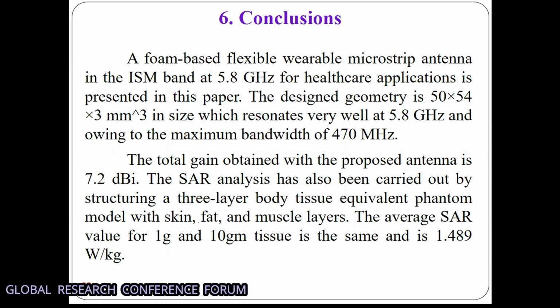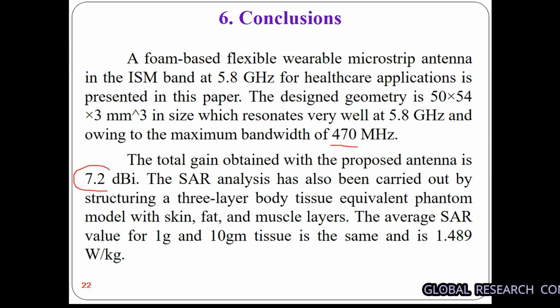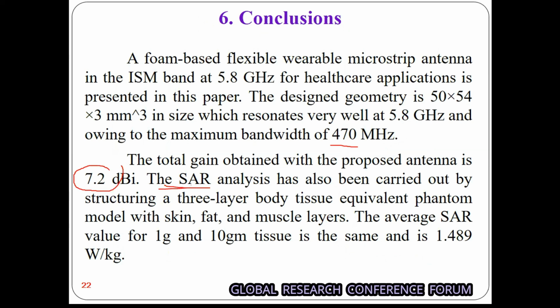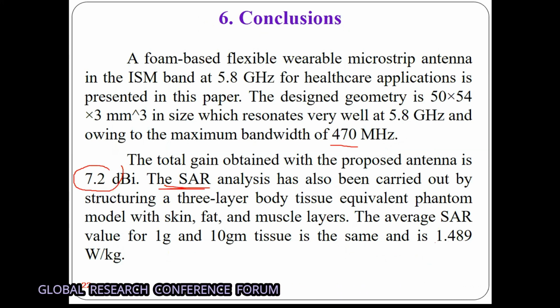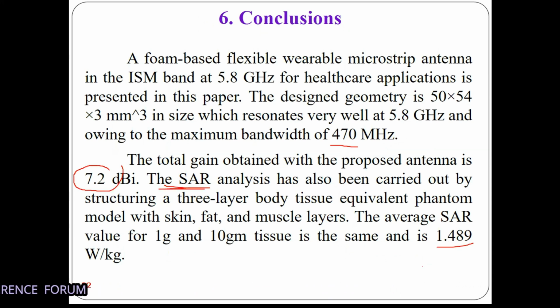This is the conclusion. I have obtained a bandwidth of 470 megahertz for a gain of 7.2 dBi, and SAR analysis was also carried out, which gives the value of 1.489 watt per kg.